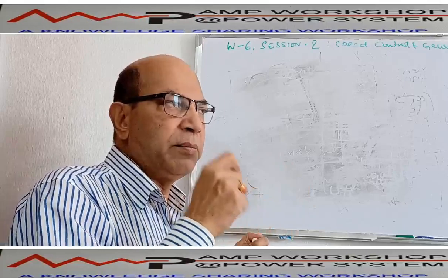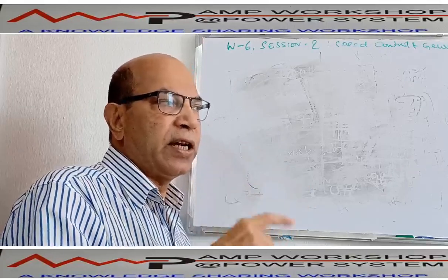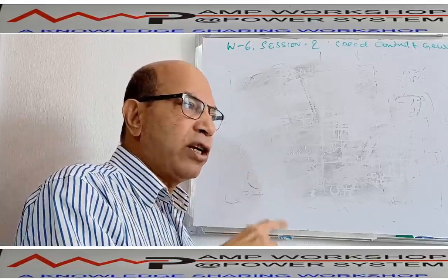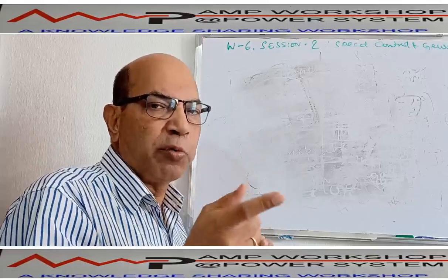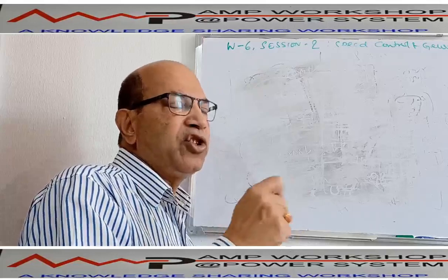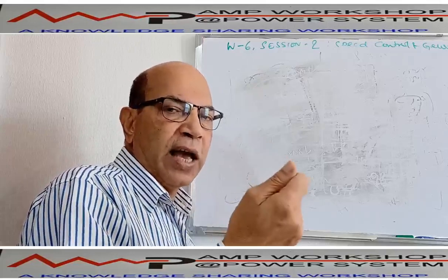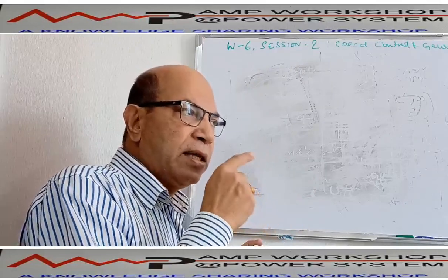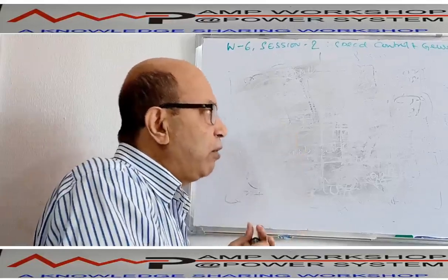Because the speed of the machine is decided by the actuator, and the actuator is operating on what basis? On the basis of the output current. By including the resistance in the circuit, we can change this current, which means we can change the actuator position. So by this resistance, we can control locally on the governor itself.